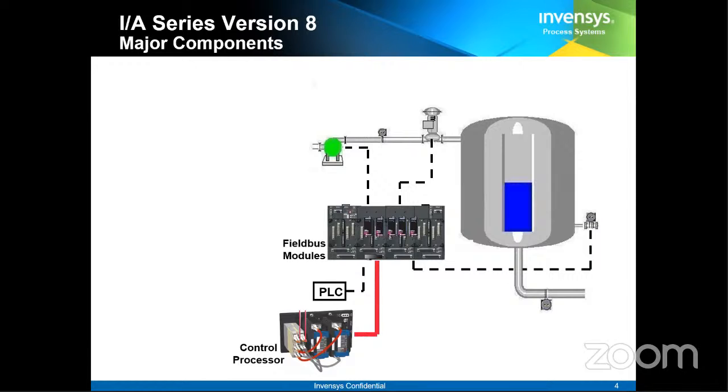If the error is very high, the derivative control will try to bring it down as much as possible. Once the error comes down, the proportional and integral will come into the picture. From that point, they will take over and bring the error value further down, to or near the value 0. That is how P plus I plus D, when all three work together, really fulfill our purpose and give better performance in a continuous control loop.